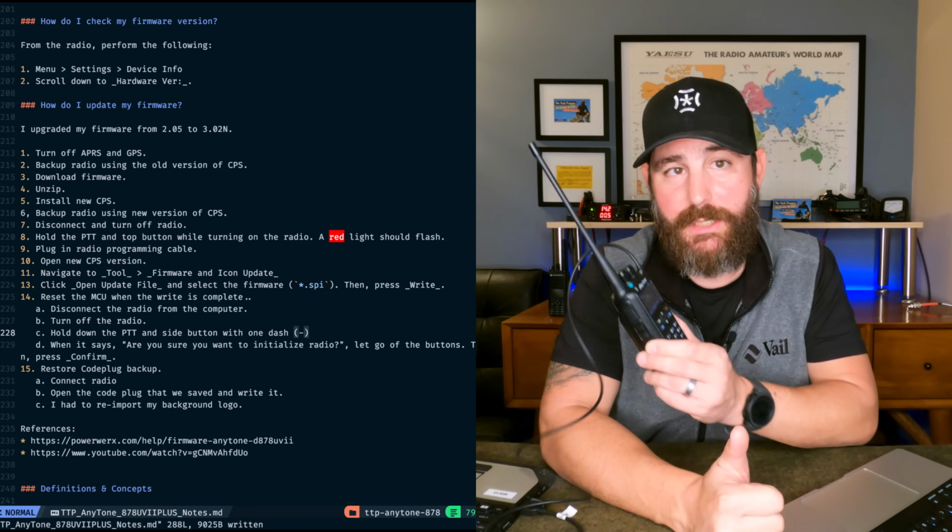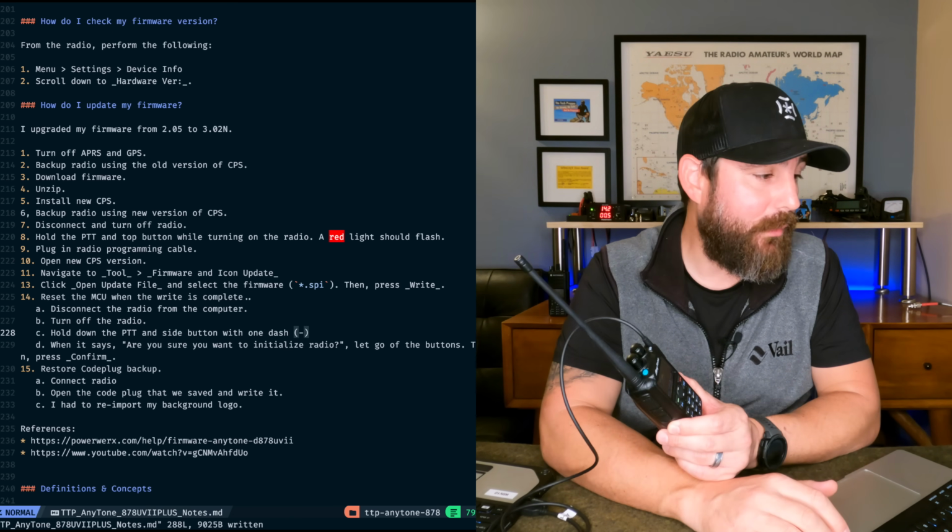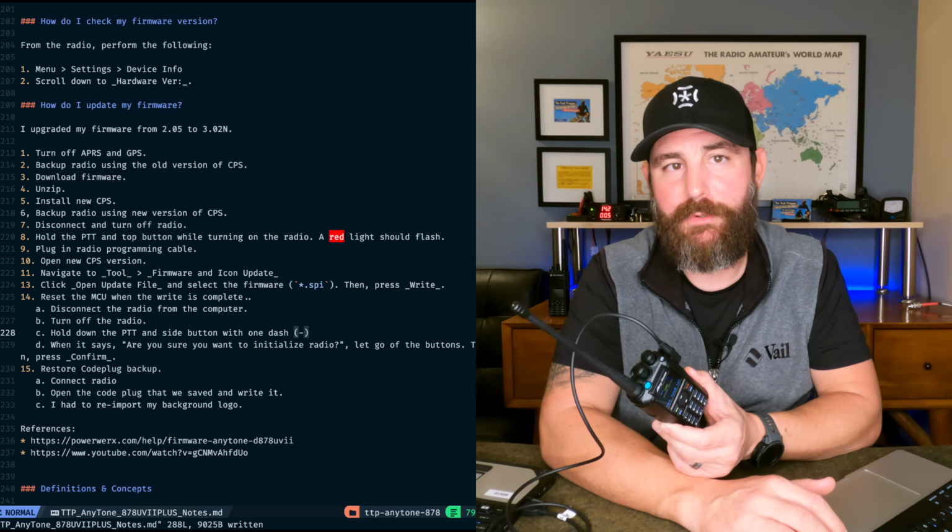So there is a process where you can download new versions of the firmware that have patches and use the CPS, or customer programming software, that we were using to load it. So that was one other thing that I wanted to do. So I had two questions here. One, how do I check what my current firmware is? And the other one is, how do I update my firmware?